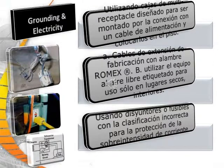Using multi-receptacle boxes designed to be mounted by fitting them with power cords and placing them on the ground, fabricating extension cords with Romex wiring, using equipment outdoors labeled for use only in dry or indoor locations, and using circuit breakers or fuses with a wrong rating for overcurrent protection all present hazards.